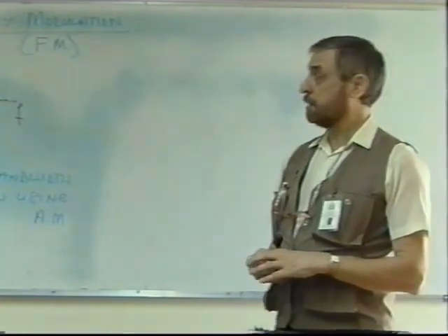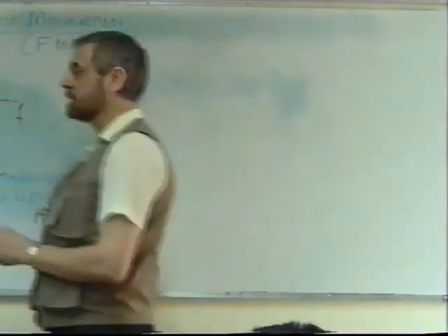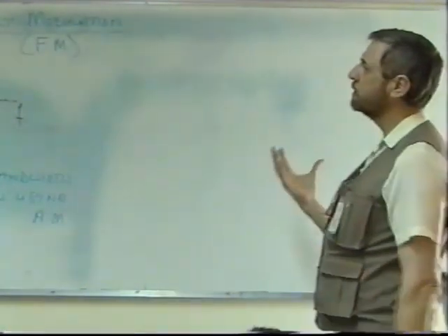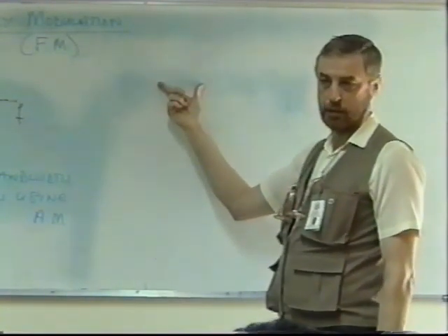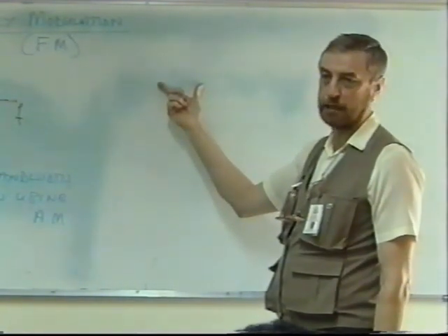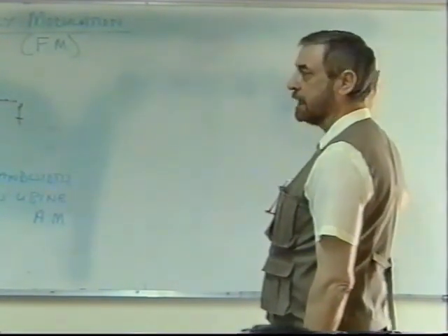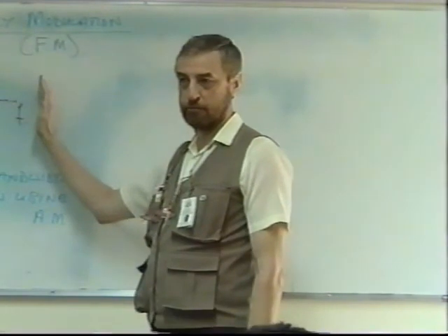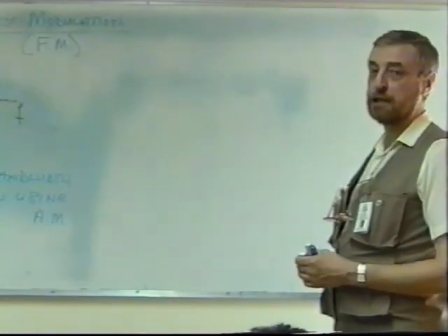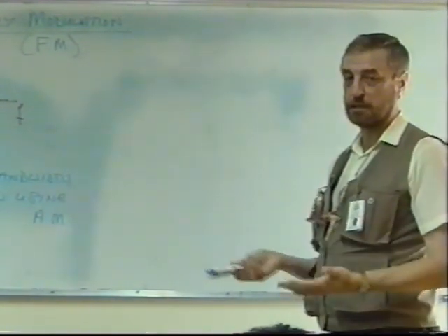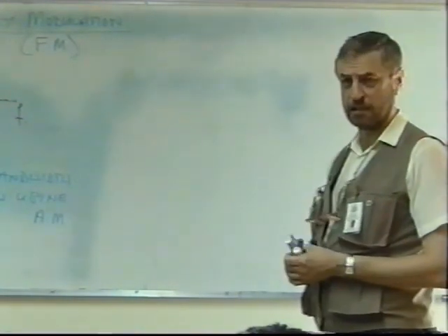Well, that might be true, but just regarding bandwidth alone, let me just say that what we've got to do is compare like with like. If I'm talking about a telephone circuit with, say, a 3.5K bandwidth, I use AM, it will take less bandwidth than using FM. Now, of course, if I choose a different example, let's say a radio broadcast, which transmits not only speech but also music, that might have a 10 kilohertz bandwidth.